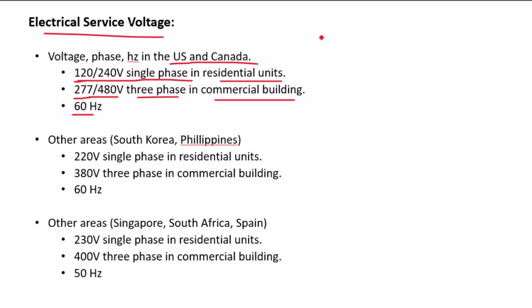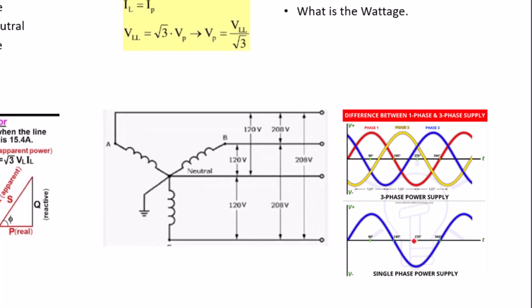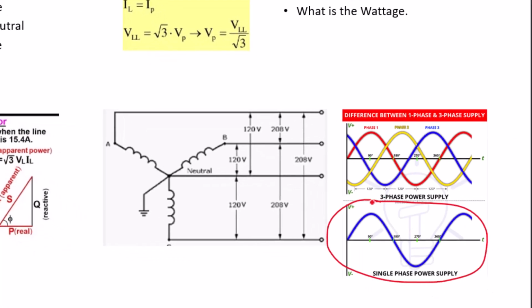In an AC system, the voltage behaves like this down here, where it oscillates up and down to the voltage specified, so basically 120 or 277, which are common ones in the US. And the Hertz, basically this is one cycle, up to this point. This is one cycle, so it's 60 Hertz. So you have 60 of these cycles in 1 second.